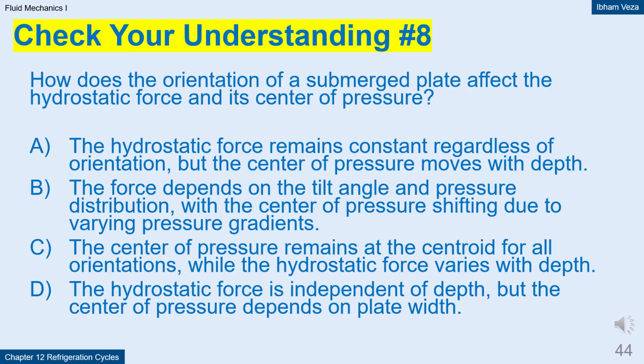Option C, the center of pressure does not always remain at the centroid. It shifts below the centroid due to the non-uniform pressure gradient. Option D, the hydrostatic force is directly related to depth, not independent of it. Plate width affects surface area, but not the fundamental depth-pressure relationship.